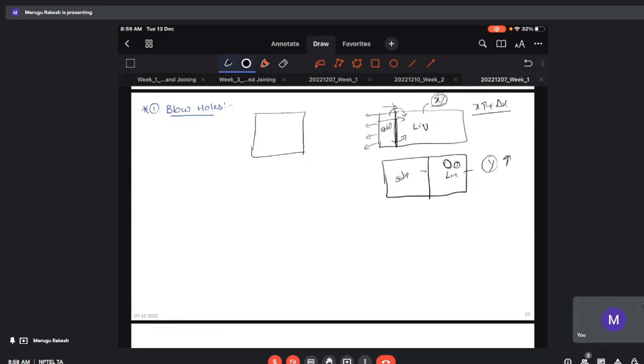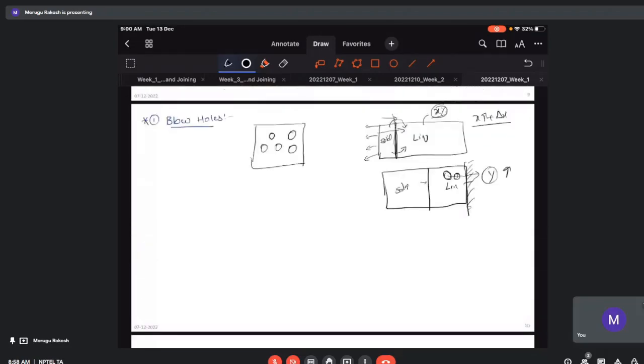If the permeability of the sand wall is good, these gases can escape easily, but if the permeability is not so good, these gases will be entrapped inside, and finally they get solidified within the castings. That's the reason why these blowholes occur. So you have to remember the permeability of sand is also very important in this scenario.